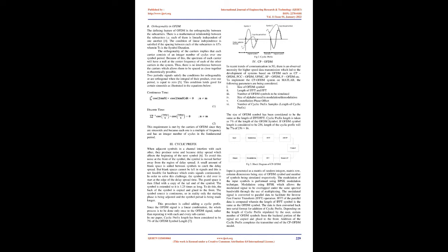This prompted the advancement of OFDM, orthogonal frequency division multiplexing. OFDM is generally utilized in digital TV, audio broadcasting, and 4G communication networks. One of the primary employments of OFDM was in digital radio. OFDM includes the passing of multiple signals over a channel that is divided into a few subchannels. Unlike FDM, in OFDM the signals are transmitted over carrier frequencies that are all orthogonal to each other. Here, it is possible for the channels to be overlapping and it further increases the transmission rate.